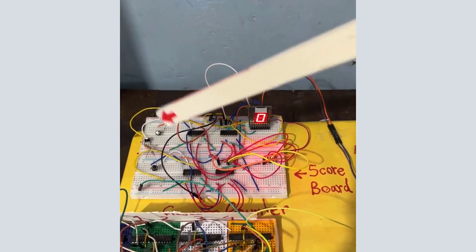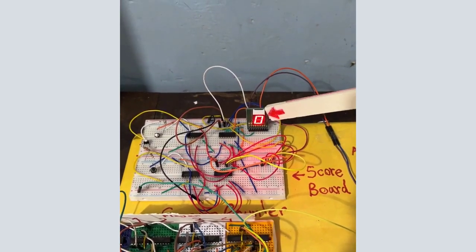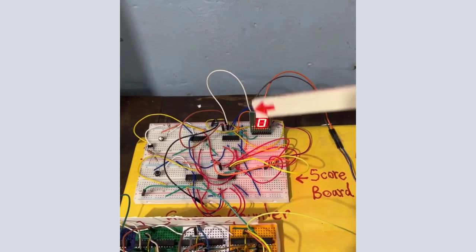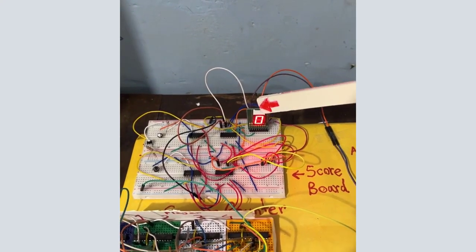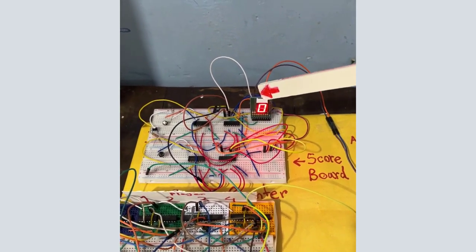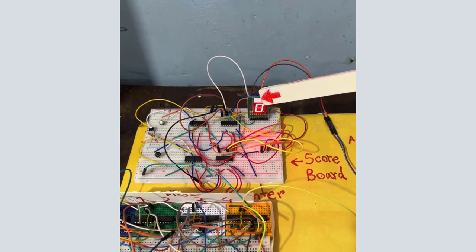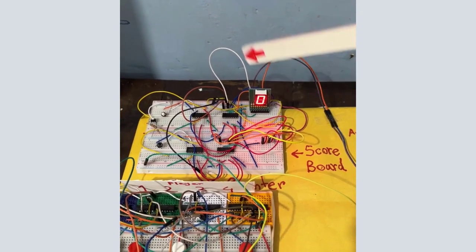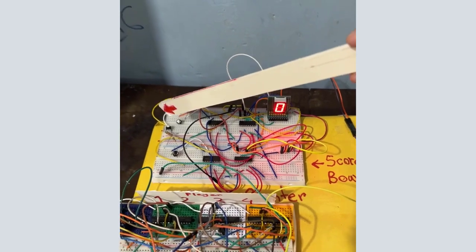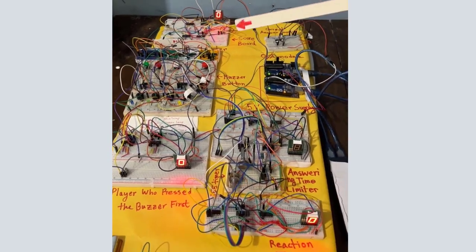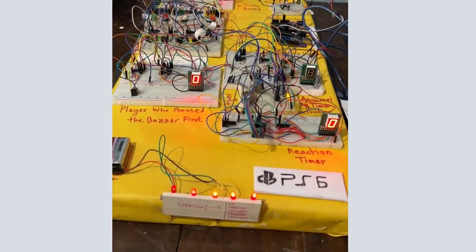Here is the marks counter board. We have implemented this marks counter only for a single player. For the other 3 players, this block will be repeated. In this section, we have used an up-down binary counter. For a correct answer, the host can increase the point by 1 or decrease the count by 1 by pressing the push button here. The player who achieves the highest point will be the winner of the game. Thus, the quiz game will go on until a player becomes the winner.